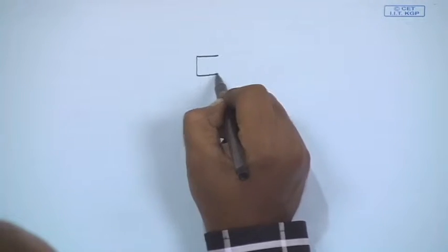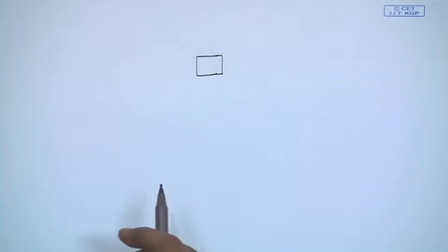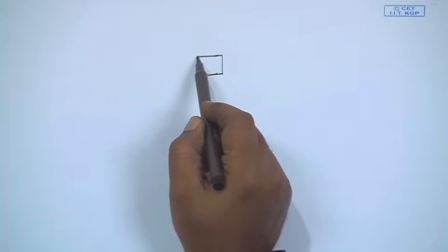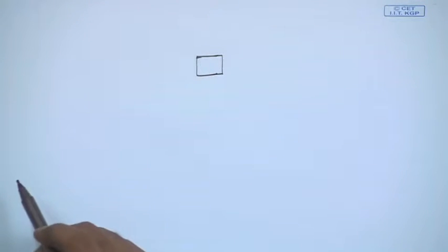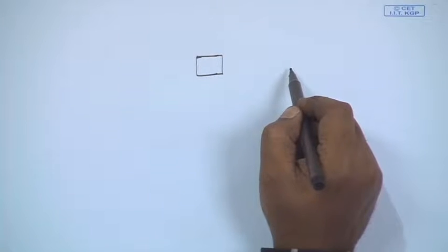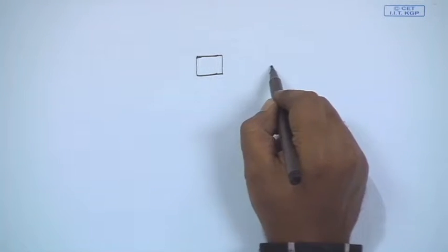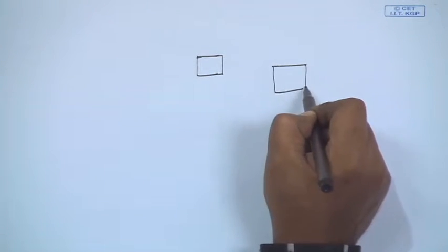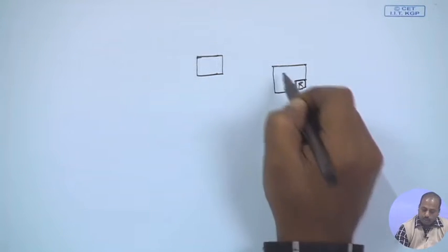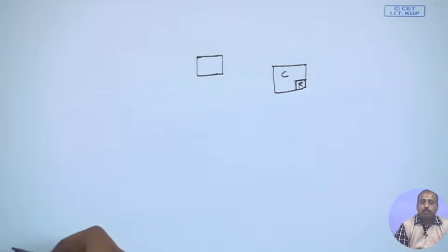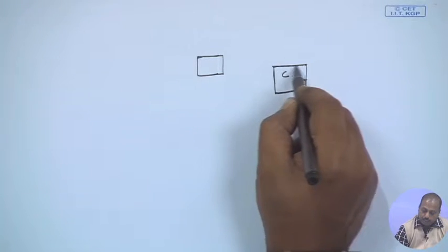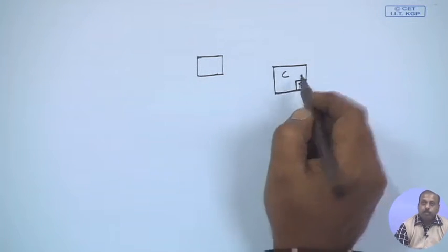The problem we have is this. In a SOC based system, if a particular core is not active for some time, we can apply some power management technique to reduce the power consumption there. But in case of NOC, the router and core are often integrated. We make a tile, and at one corner of the tile we put the router. So, this is the router and this is the core. That way the power management module comes for the entire tile. It is not for the simple router.